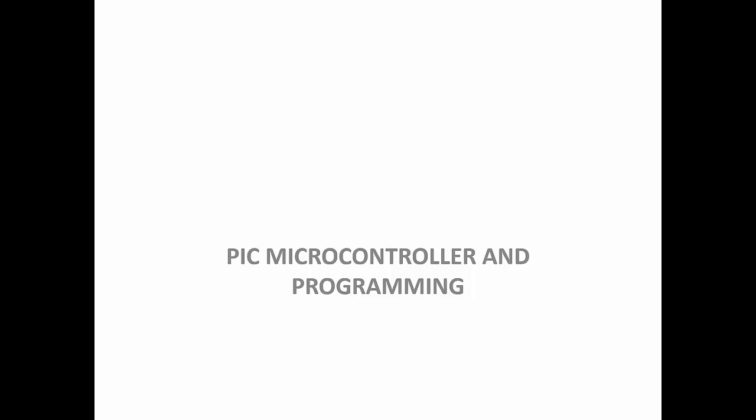So we are discussing the PIC microcontroller and programming. Today we are going to discuss another important register, that is the status register. So far we have discussed the working register, that is WREG, which acts as the accumulator of a microprocessor. In the case of your microcontroller, it is WREG. Similarly, for arithmetic and logic operations, the status is given by this status register.